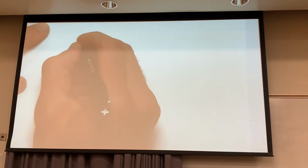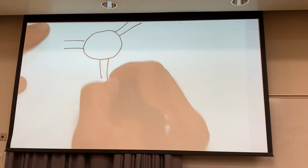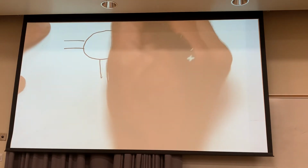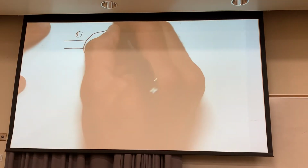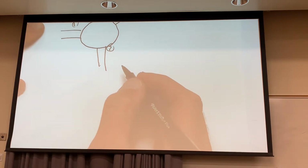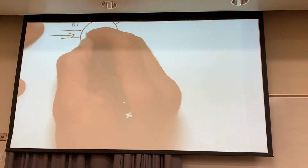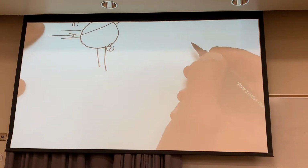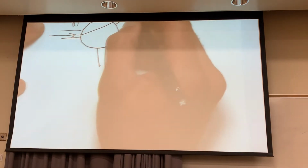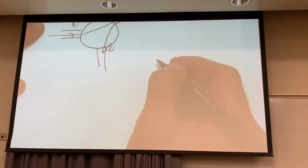So here's what a circulator looks like. They're going to have basically a ring like this. If you can tell me the page number, I'd appreciate it. 568. Page 568. So this is port 1, this is port 2, this is port 3. And here's what the circulator does. It's sort of a roundabout for electromagnetic energy. Anything coming in here wants to be shunted and come out there. That's the ideal. It'd like all the signal that comes in port 1 to be shunted out port 2, anything coming in port 2 to be shunted out port 3, and anything that comes in port 3 to come out port 1.